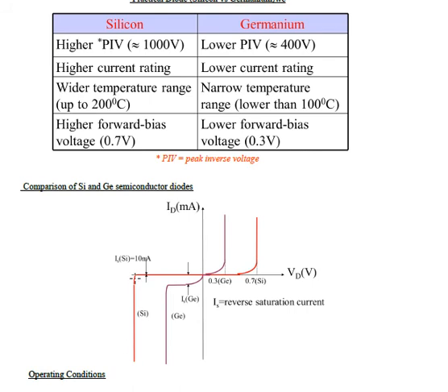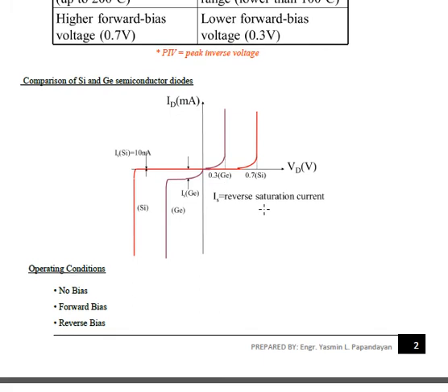the diode requires first 0.7 volts in order for it to conduct a current. No, so first kay zero muna yung kanyang current, then after it reaches the voltage of 0.7 volts, it will conduct. No, and for the germanium naman, okay, so meron tayong negative value of the current, and after it reaches 0.3 volts, it will reach a maximum value. Okay, so these are the basic characteristic and graph of the germanium and silicon.